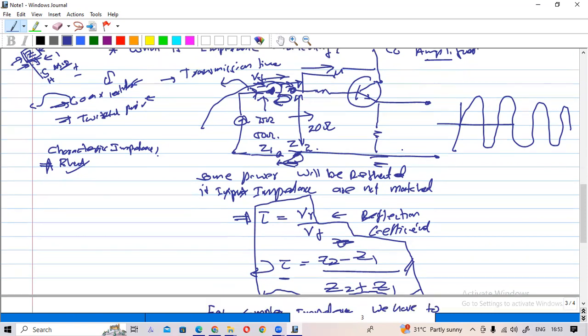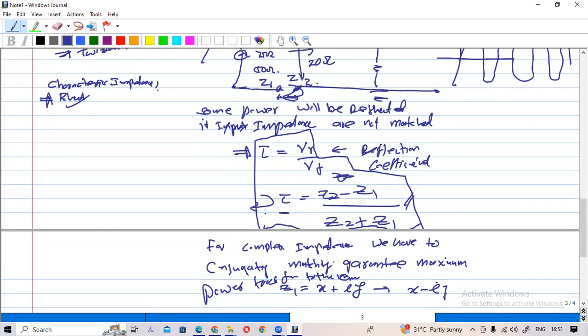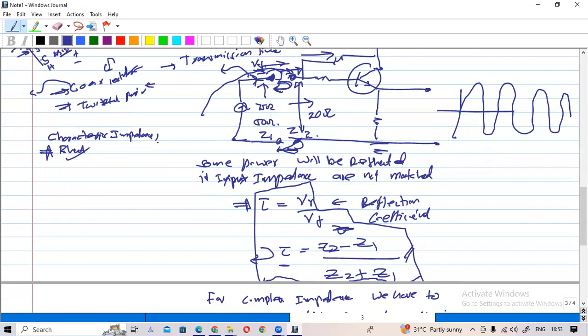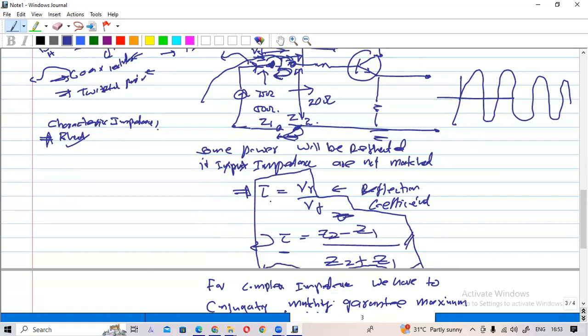So you can write this if you need it. Impedance matching is for when the signal is transmitted from one impedance to another impedance, the signal will be reflected due to unmatching of the impedances. That reflection is actually VSWR. I think most of you know VSWR happens due to this problem. Telecom students know what VSWR is. VSWR is defined using this reflection coefficient.